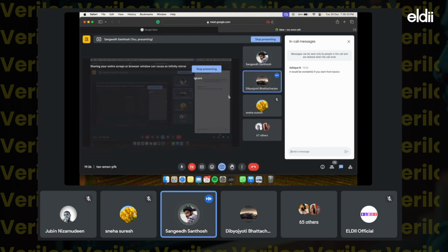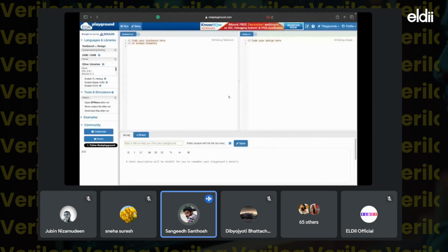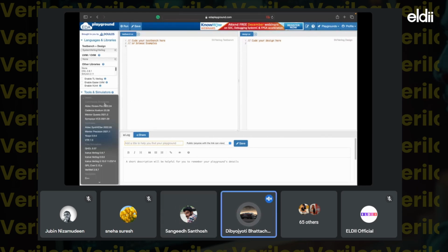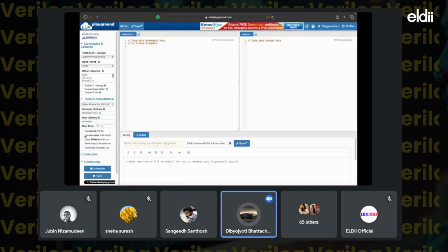So we need to export that into dump.vcd to open in EP wave. It's just a standard procedure to open EP wave. Okay, sir, so this is not directly connected with our design? For EDA Playground only, we need to use that statement. If we don't do the dumping, then we can't access the waveform in EP wave.